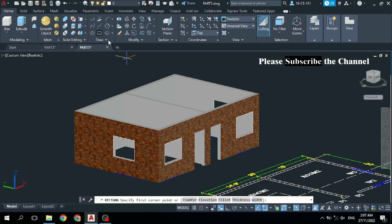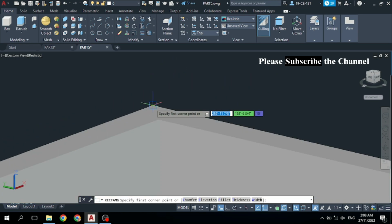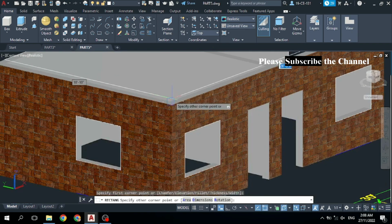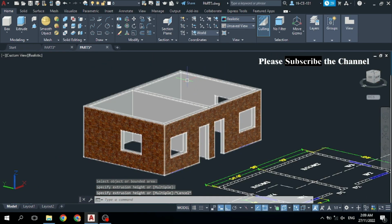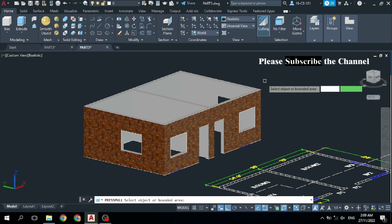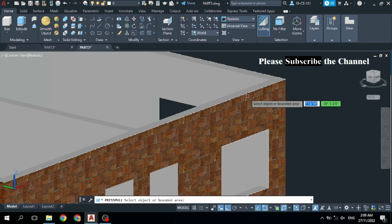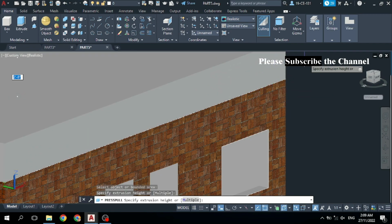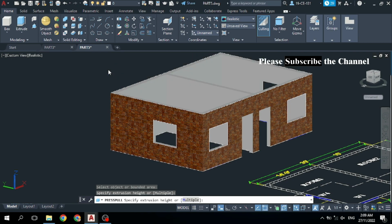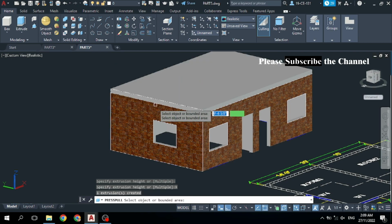home and click on this rectangle command and start from this corner and come and click at this corner, finish at this corner, and after that come to this press pull command, click on this press pull command and click inside this big rectangle. Simply click at this side, click on it. Now you can see go upward by 9 inches upward. This is roof 9 inches, and after that select this space.